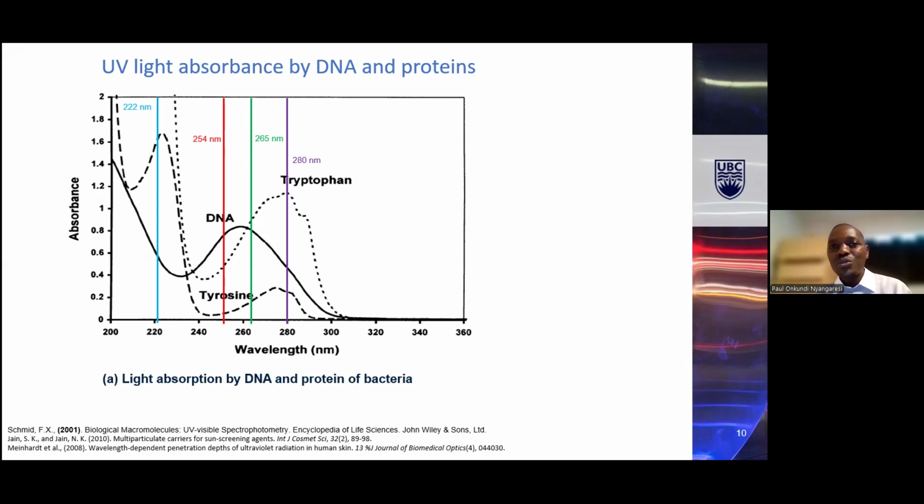And then the other thing which you have to ensure and look up to is the flow rate of the system. What's the flow rate? Because if the water is flowing very fast, then the microorganisms in the water have less time to absorb the UV light. So you have to ensure how you have designed the system itself and what power the system has. And then from there, you can know which type of system you need to use for that kind of water treatment. So if this UV system can kill MS2 at this rate, and it has this power and this flow rate, then you are very sure it will be able to perform its function.